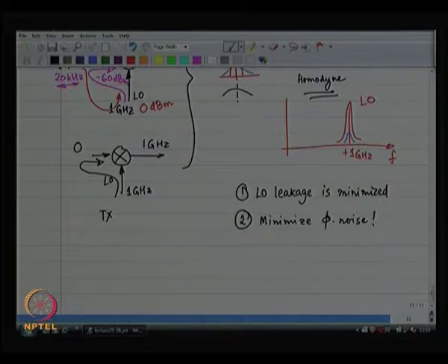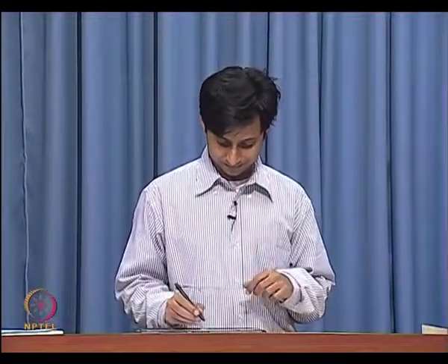There is phase noise associated with it, and when there is phase noise associated with it, I will get the square of the phase noise on top of the DC. Is this a problem? What does the output spectrum look like?